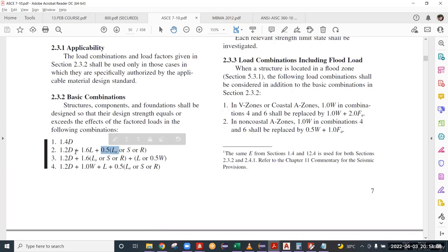And there is no wind load. If there is full wind load acting on the structure, would any person want to go over the roof for maintenance? No. So that is why practically they have chosen this case for maintenance. So 1.2 dead, 1.6 mezzanine live load.